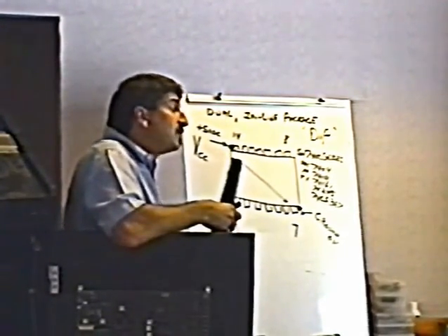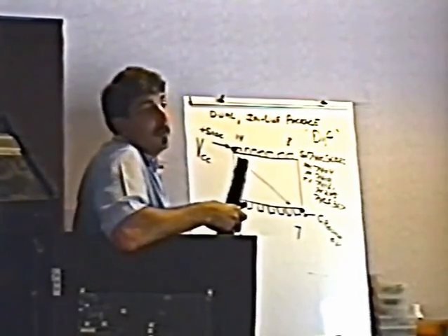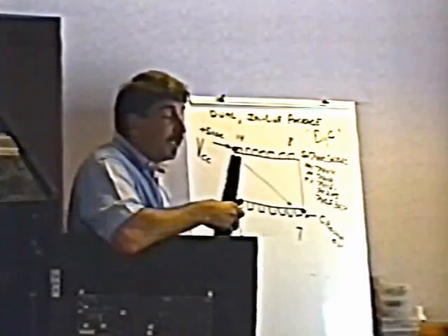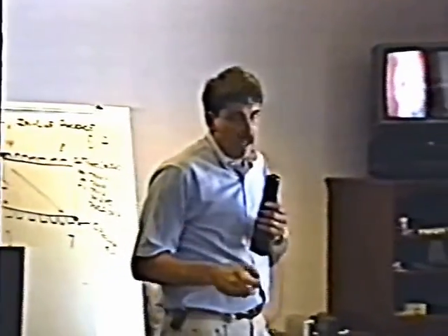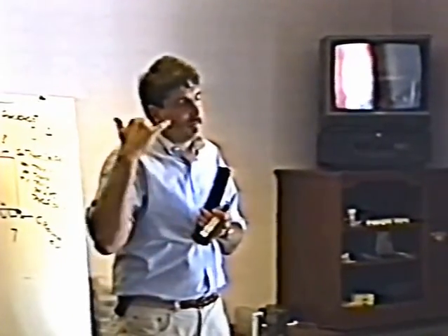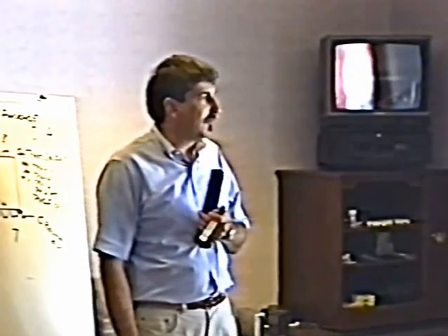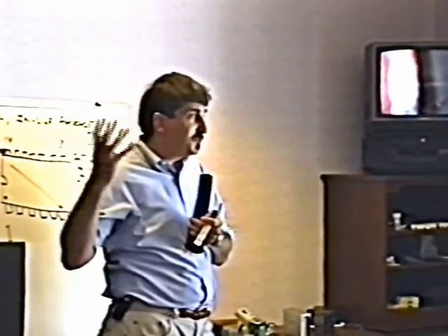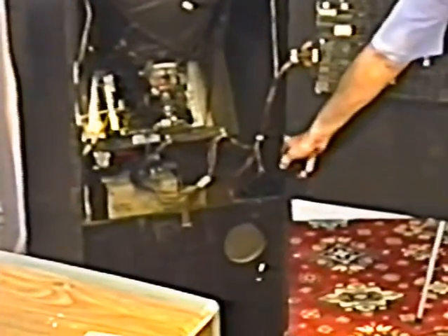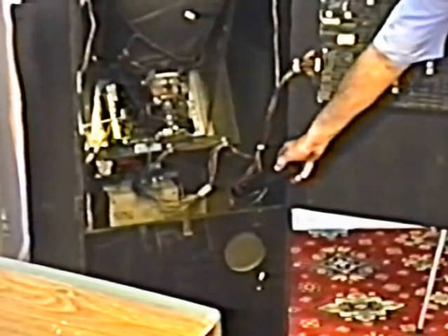This is the number one cause of people sending their boards into the distributor for repair when there's not really anything wrong with them. What happens is someone gets to the game and let's say the game's doing some kind of wacky things like shutting off intermittently. You get this complaint, the location says, yeah, the game just froze up or whatever. They turn it off, you get there, you turn it on, of course it works perfectly okay for you. Or weird bits of graphics and weird jazz on the screen, all this kind of stuff. This may just simply be a power supply problem. And what happens is people measure the voltage down here at the power supply itself, down here inside, set it to exactly 5 volts.